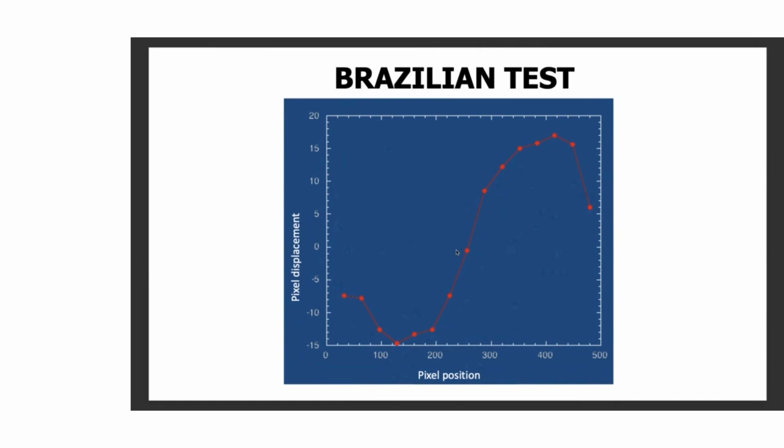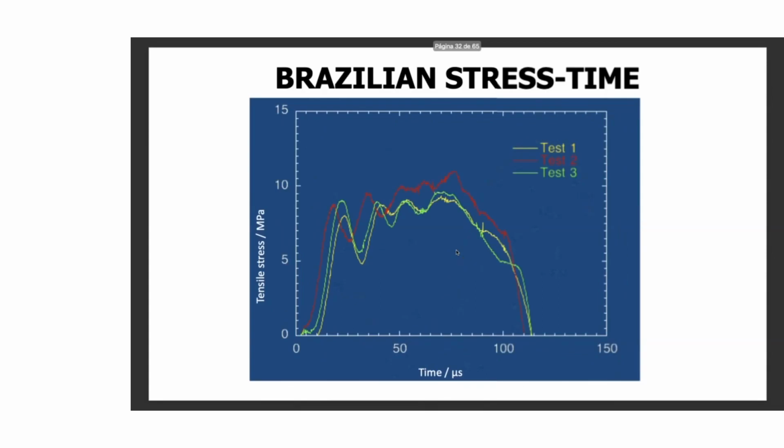And what we find for these type of polymer bonded systems is that fairly straightforward, simple equations that predict the stress existing in a disk under this type of loading match very well with the data that we've obtained. So everything seems to be behaving itself, and that's a good thing. We can look at the stress time results and get those tensile stresses in the sample.